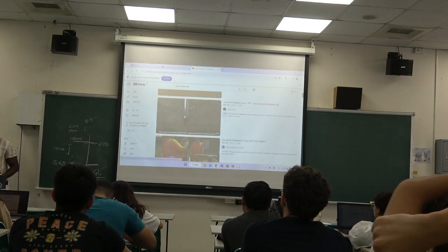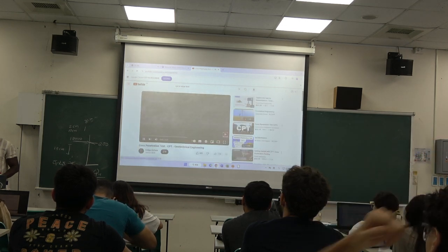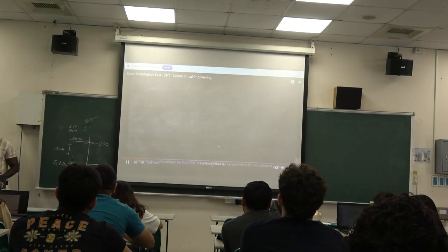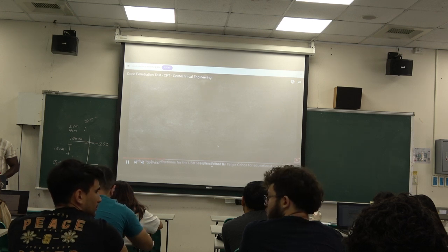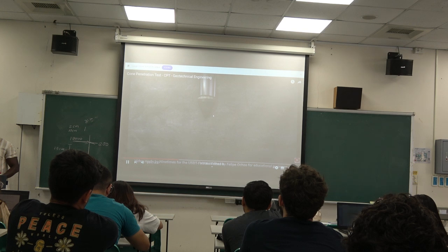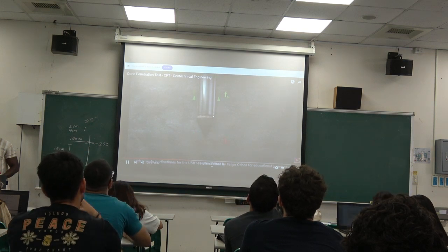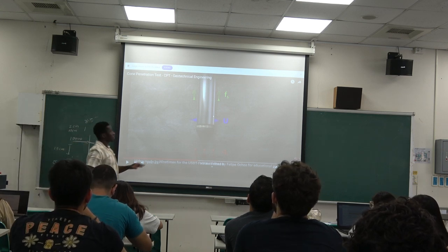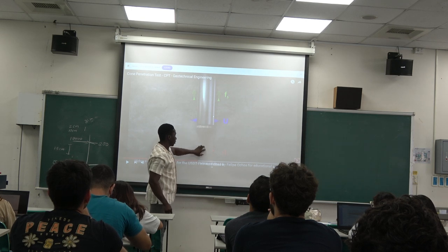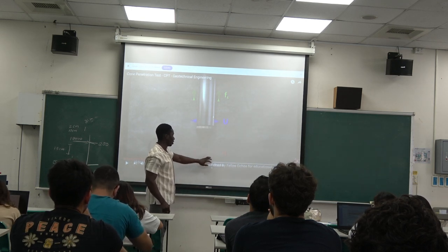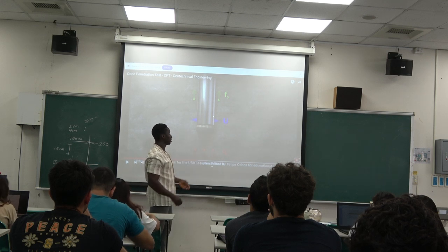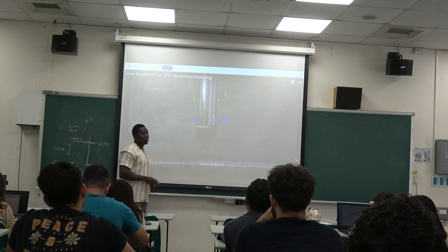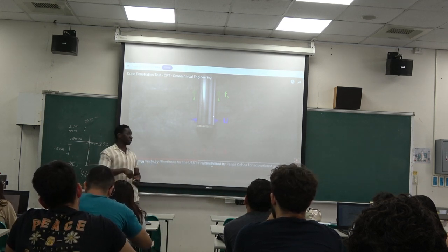The concept, okay, this is the CPT. You can see here, you have a cone, and then you push it into the ground. So here we have the QT, that is the resistance at the tip. And then they have another instrument here that measures the U. The U is the pore water pressure at that specific location.